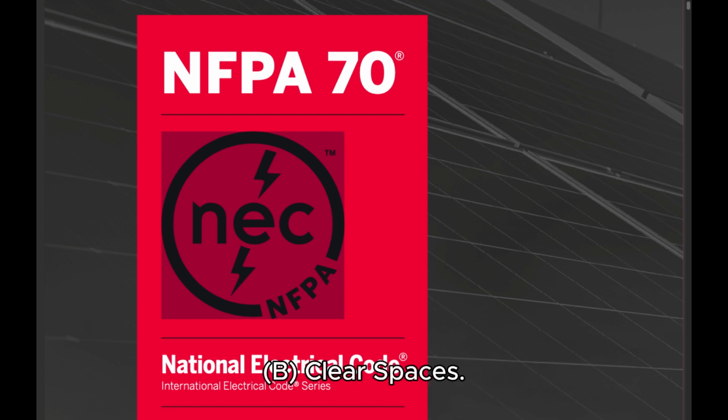B. Clear spaces. Working space required by this section shall not be used for storage. When normally enclosed live parts are exposed for inspection or servicing, the working space, if in a passageway or general open space, shall be suitably guarded. C. Entrance to and egress from working space. 1. Minimum required. At least one entrance of sufficient area shall be provided to give access to and egress from working space about electrical equipment.